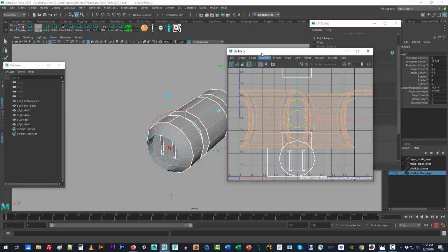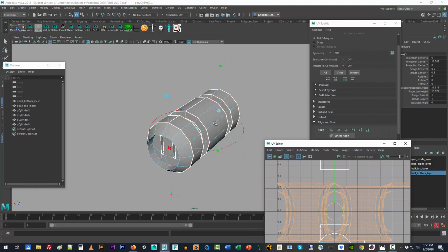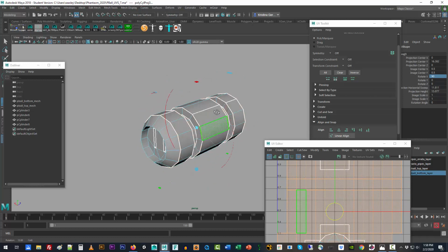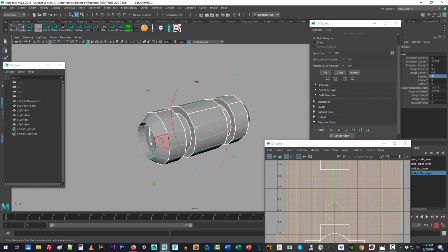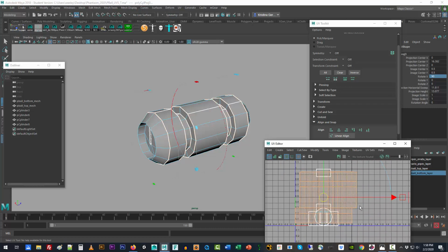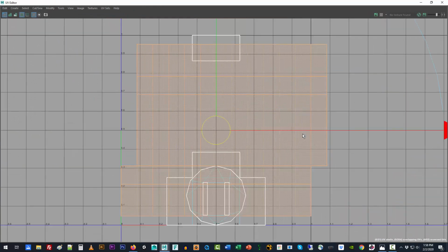So what we want to do is, while we're still in the mode where it is giving us our projection to map, come up here and rotate the projection itself by 90 degrees. So you've turned the projection on its side as well, and now we have a nice cylindrical mapping that's adhering to the way that we have our cylinder. And you can see it's a lot more of a coherent map. There is a small little detail that one of these blocks is kind of knocked off down here at the bottom. Right about here is where you see that this stair step is a bit odd.